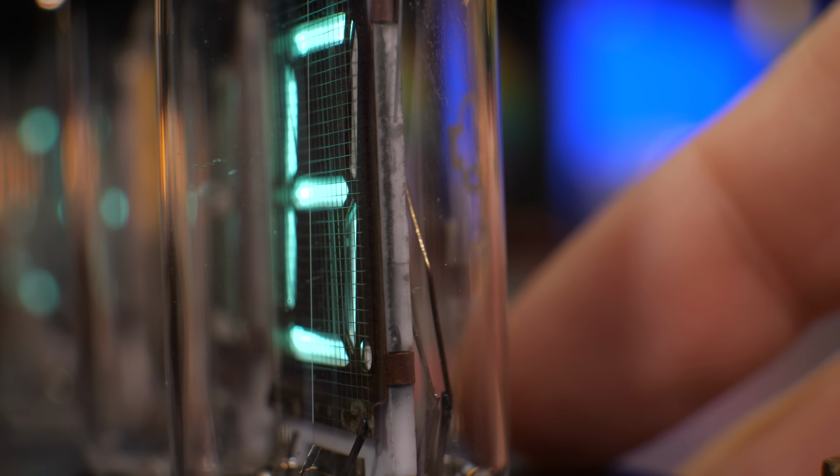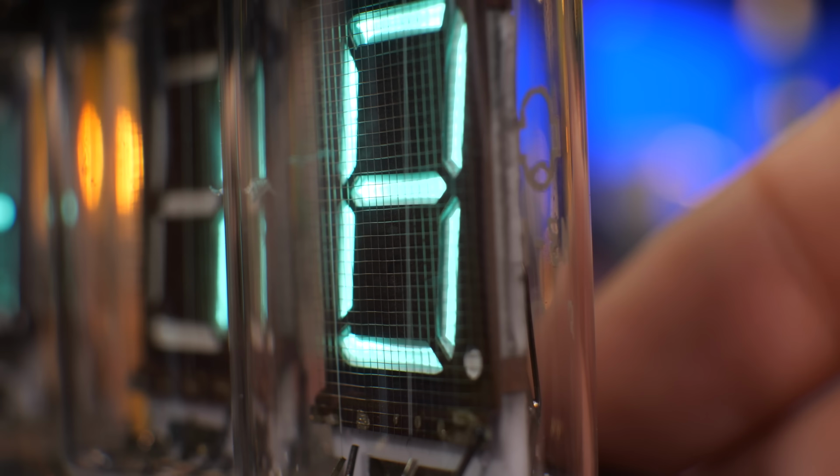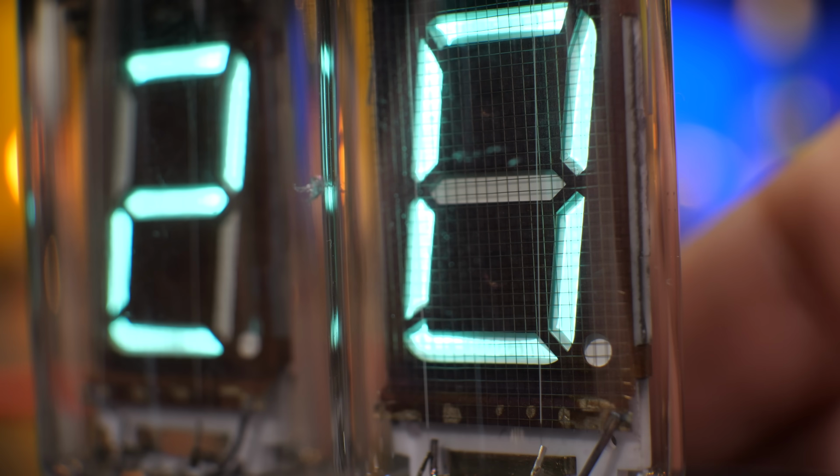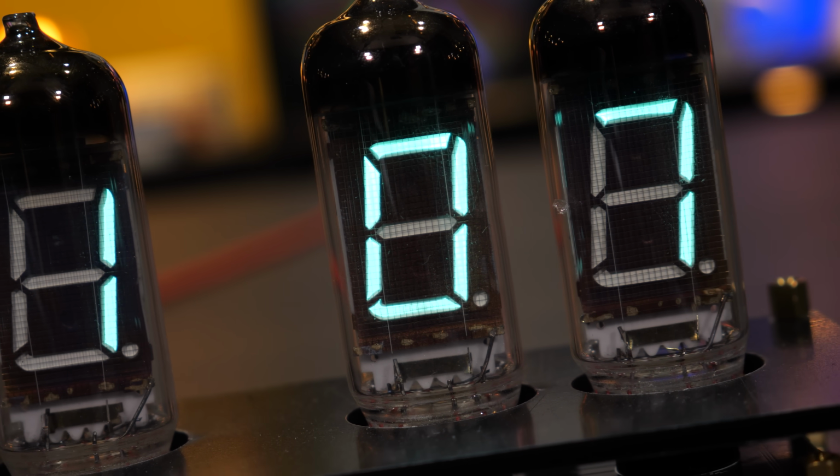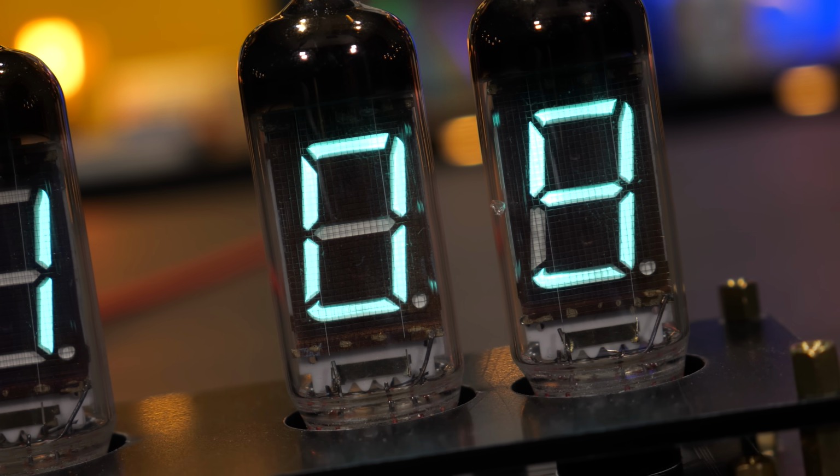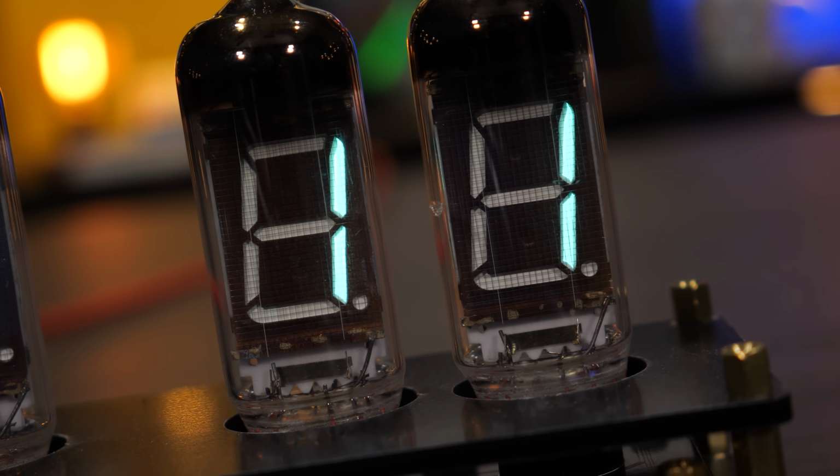These tubes didn't need high voltage, but they needed 2 voltages, a low voltage for the cathode wires and something around 30 volts for the anodes and control grid. Better than 180, of course, but still much higher than the logic circuitry of whatever you want to put these in, which was typically 5 volts. And as you might be able to tell, these early tubes have pretty poor contrast under even modest ambient lighting, since the phosphors are white when unlit. So, both neon tech and VFDs had their problems.